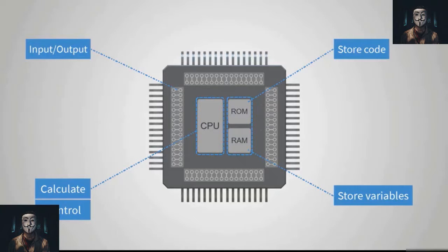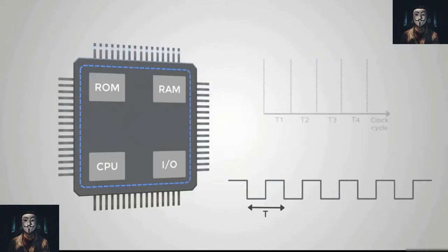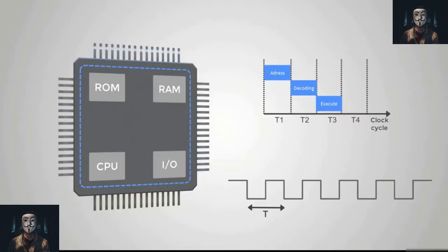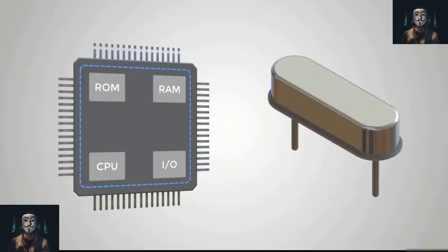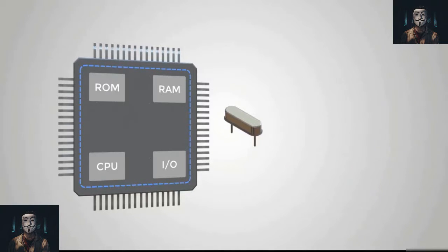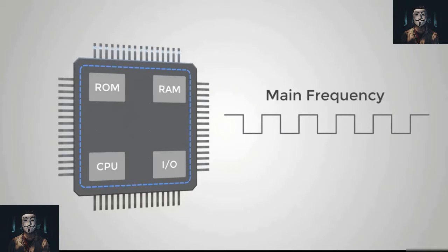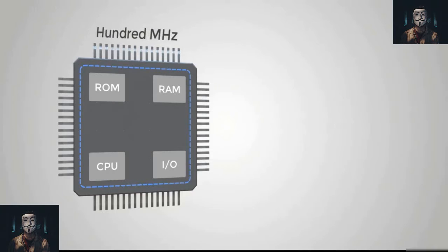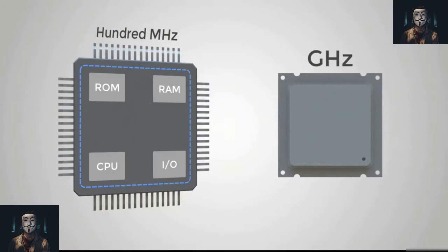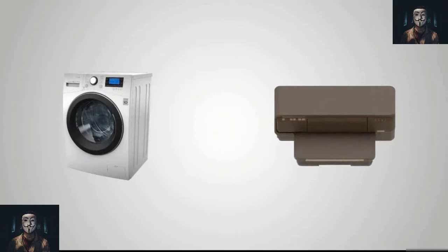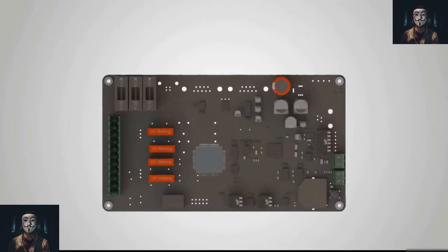On the whole, though, microcontrollers can be said to function usefully on their own, with a direct connection to sensors and actuators, whereas microprocessors are designed to maximize compute power on the chip, with internal bus connections rather than direct input-output, to supporting hardware such as RAM and serial ports. Simply, coffee makers use microcontrollers, but desktop computers use microprocessors.